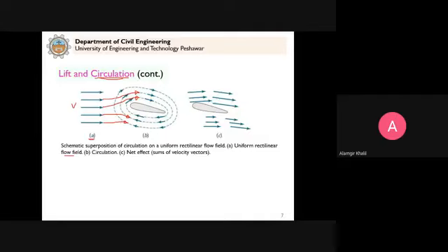So now there is a circulation and the fluid flows past this object. You can see that both the velocity vectors here and here are in the same direction, so they add up. So that's why V increases. This is the reason that V increases at the top of this object.